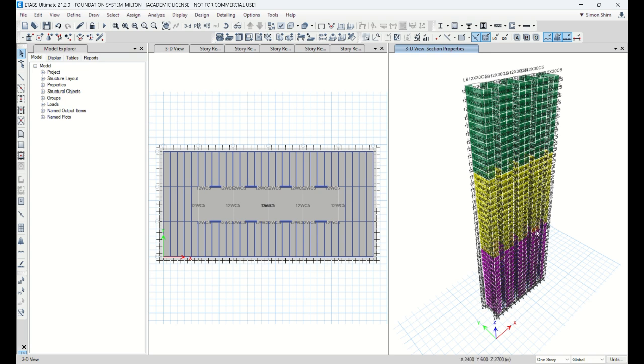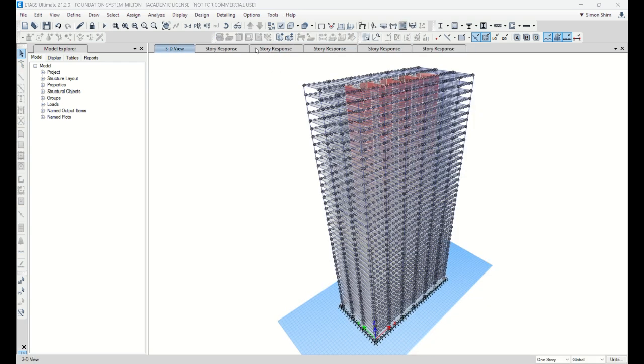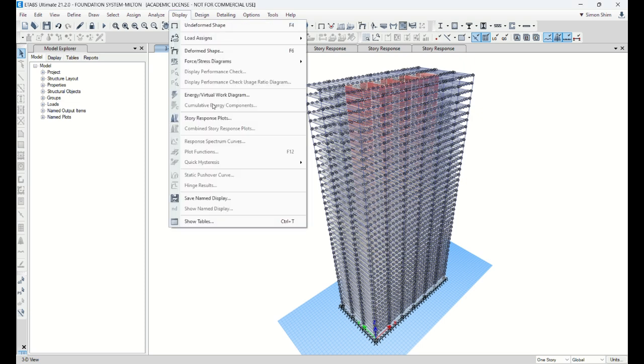The wall thickness varies 24, 18, 12, but with the various concrete strengths. So I'm gonna save this. Let's run the model. I'm sure since we're using a thicker wall thickness at the bottom, the deflection will go down. Running. Okay, I'm just pausing. All right, so analysis is done. I'm gonna just double check again.